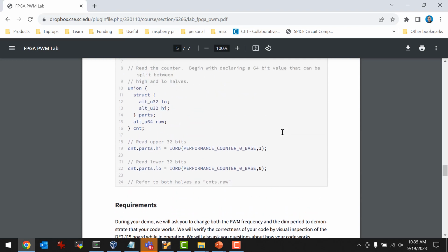Yeah, we noticed something over the past couple years. The problem is that the Nios processor is a 32-bit processor, and at 50 megahertz, if you have a 32-bit value and you increment it once every clock cycle, it'll roll over in 43 seconds. You think a 32-bit value goes up to 4.2 billion, yeah, but at 50 megahertz, it'll roll that odometer around in 43 seconds.